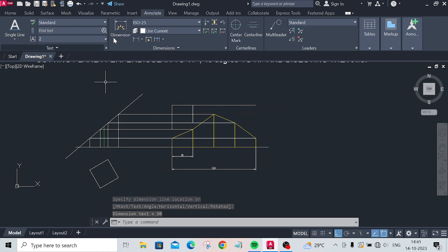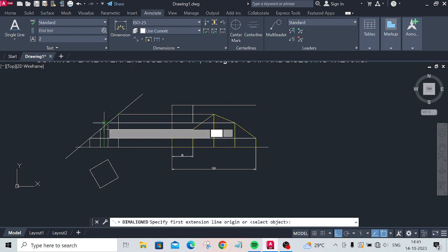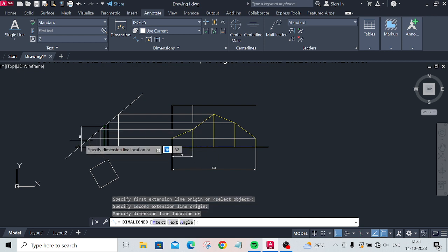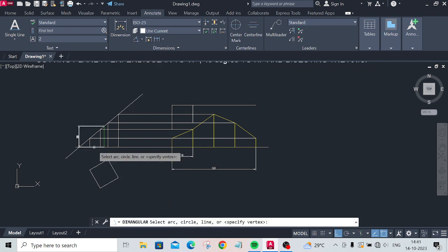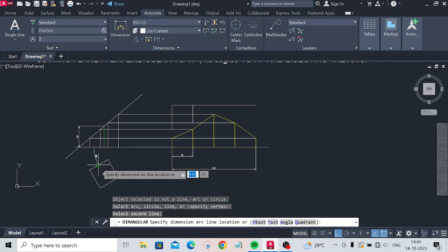Other things: the cutting plane passing angle, passing height, that also you should provide. This is 30 mm, because in the middle it is passing through the axis, and this inclination also you should provide, the angular inclination of this VP to the one side.